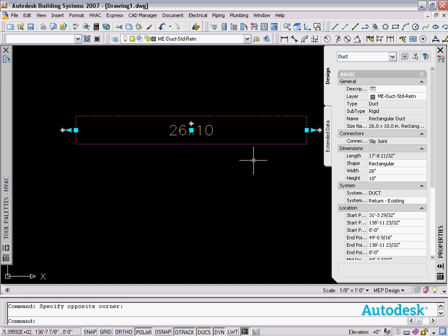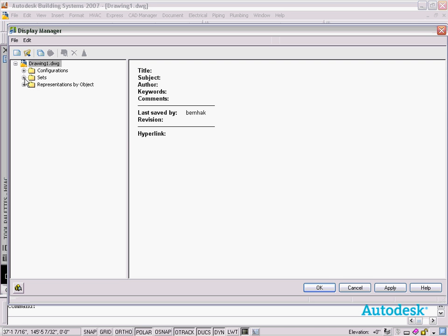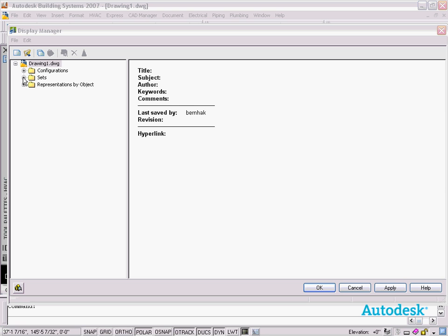That is an override over any of the settings on the system because the display manager makes changes in a global way, essentially overriding any of the layering that's been set by the system definition itself. So the duct system or pipe system would be overridden in that scenario, again because the display manager sets down global settings.